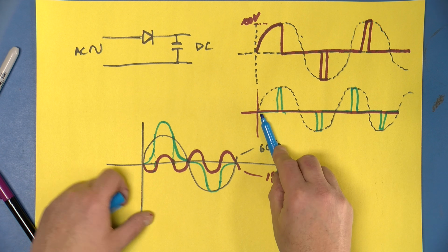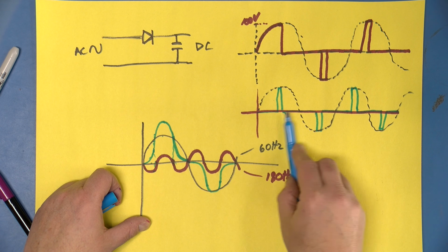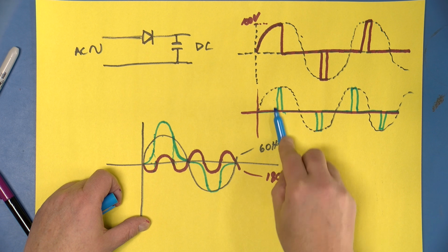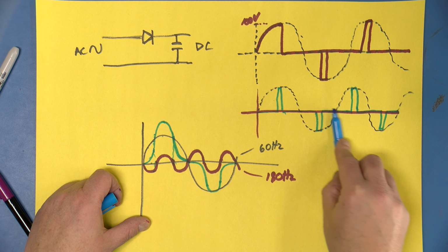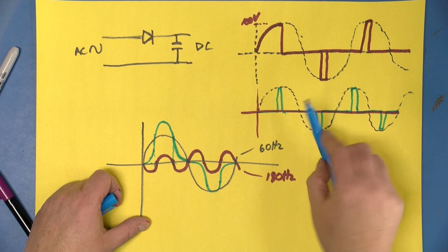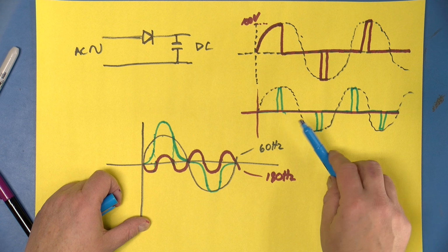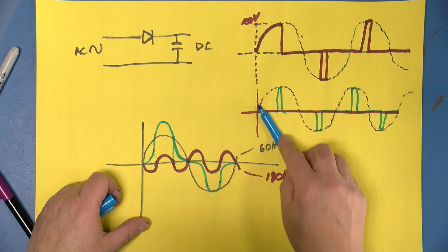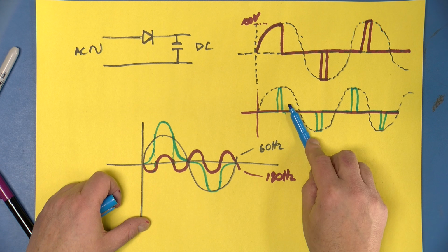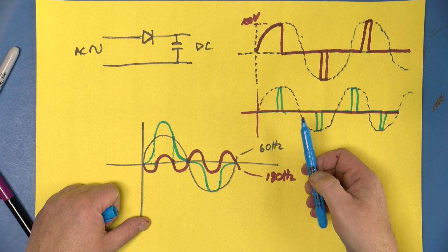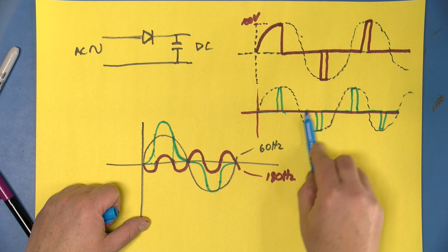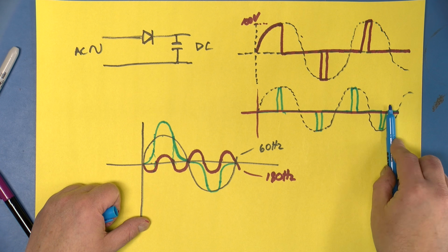The power company requires people to try and prevent these spikes. It's kind of hard to characterize how bad they are. Maybe the best way of doing it that I've seen is to do something like compare the energy in the fundamental frequency with the energy in all the harmonics, and that could be considered something like a power factor for these spiky type power supplies.